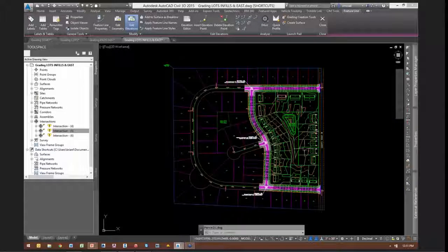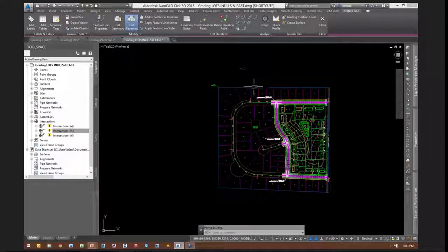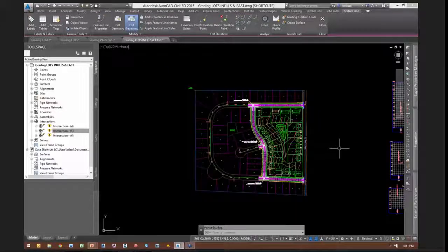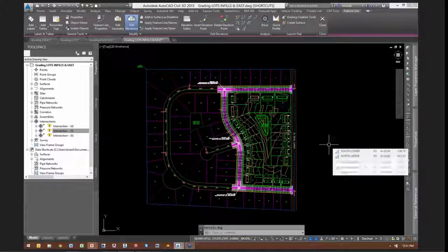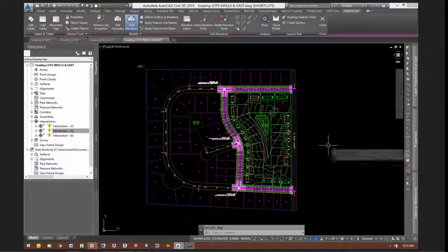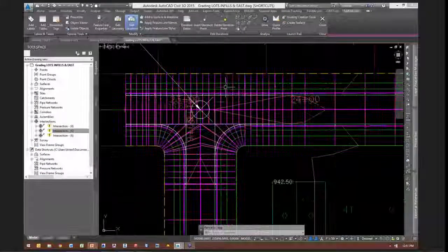For a limit of how much you could put in one drawing, putting all of this in one drawing, I would say it would be about the max limit, and that would be assuming you have a decent computer, and you're employing things like turning off surfaces and unloading XREFs, and you're freezing layers of objects that you don't need to be seen at that point in time. But that would likely make a pretty good sized drawing, but still workable.